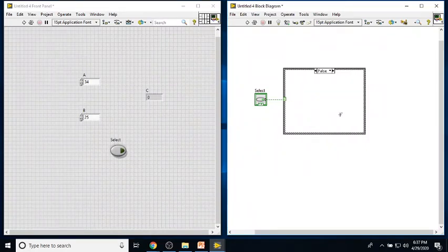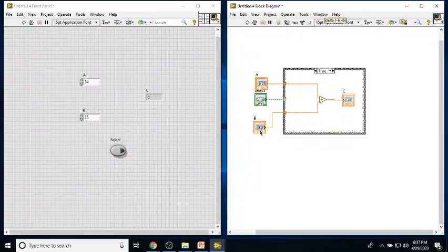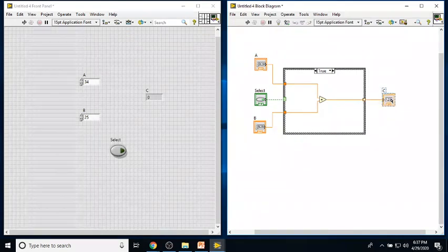This is the issue I was telling you about. If you see that these inputs and outputs are common for both the frames, am I right? When you find some items are common that you have to access in both the frames, then your job is to keep them commonly outside like this. I'll move it outside, right? I'll move this also outside, because the indicator is also supposed to be kept outside because it has to be accessed by the false case also.